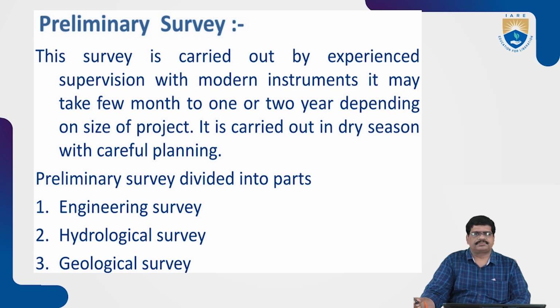So next, the preliminary survey. This survey is carried out under supervision with modern instruments, and it can take a few months for the investigation. All aspects are taken, however, depending upon the size of the project, and it is carried out in the dry season with careful planning. The preliminary survey is divided into parts: engineering survey, hydrological survey, and geological survey.